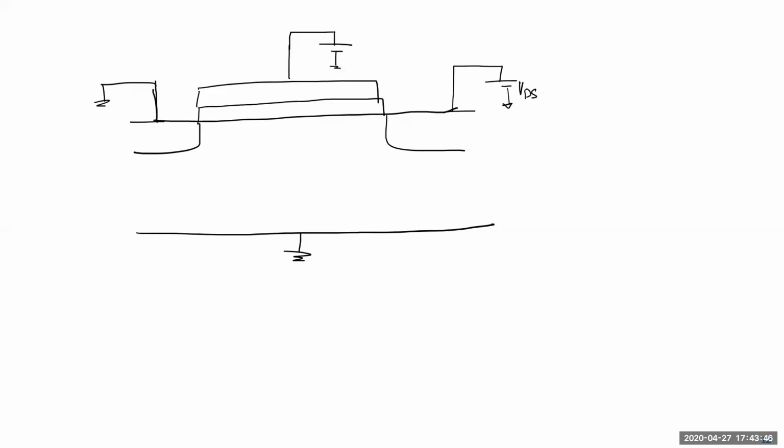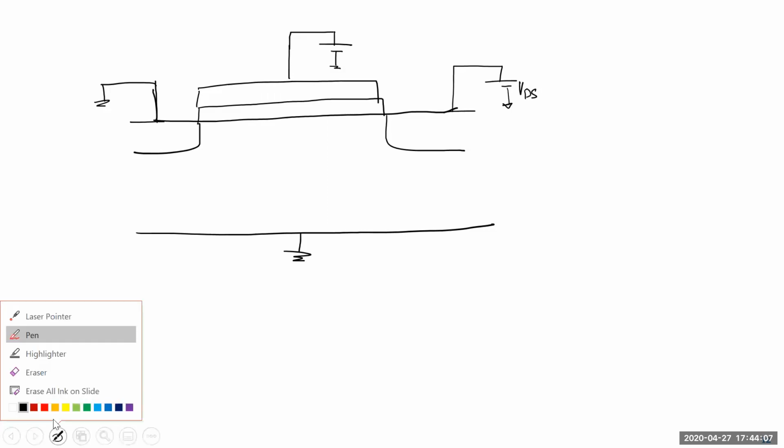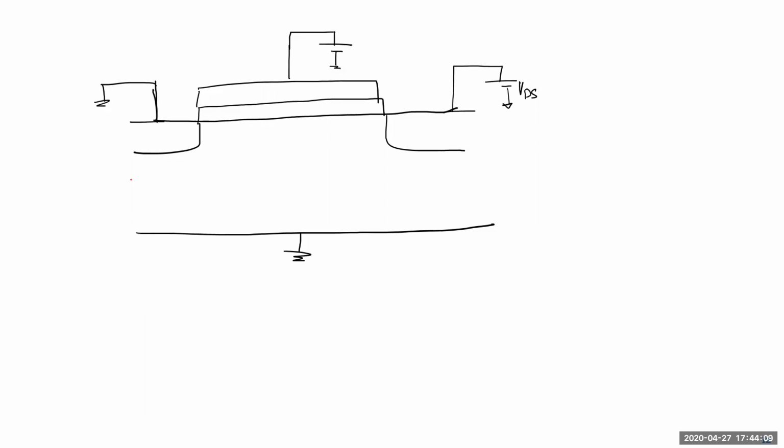No, see, that's where the confusion comes. When the depletion, because of the diode, increases, the surface potential actually drops. It doesn't increase. That's why you have to increase the surface potential to come back to that point. And that's why I said it's very confusing. So for example, this was your original depletion.